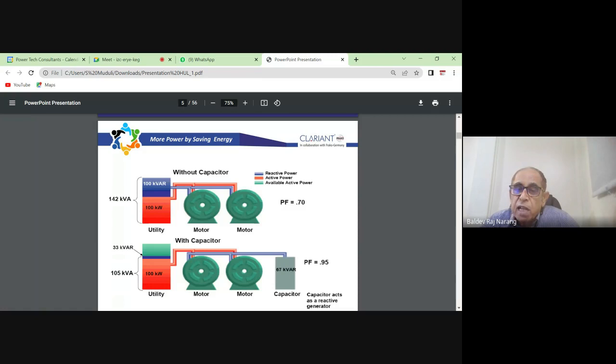As per the new kVAh tariff structures, we need to maintain power factor close to unity, where the reactive power import from the grid is 0. So if we have unity power factor, we don't have to import anything from the grid. We are self-sufficient, and we can manage at our end without any reactive power support from the grid. And the billing also is now as per kVAh billing. So this is what the scenario is today.